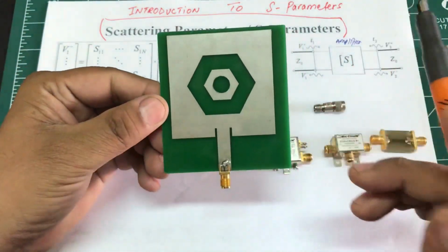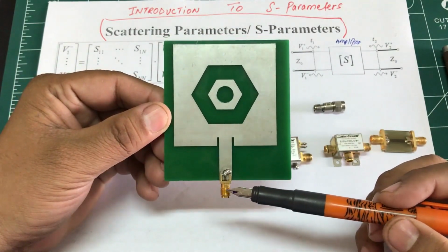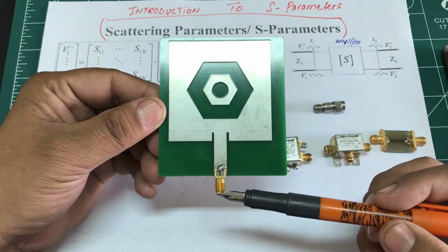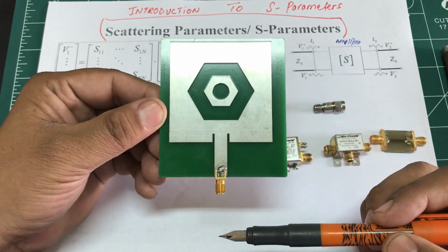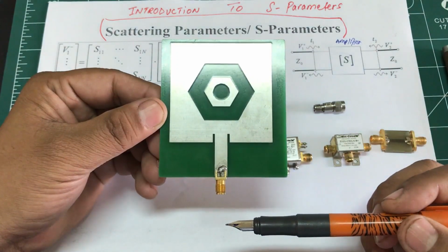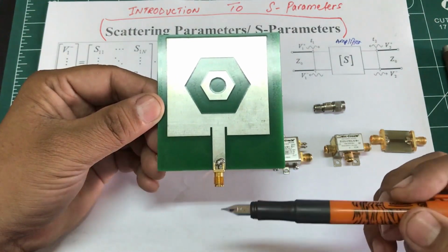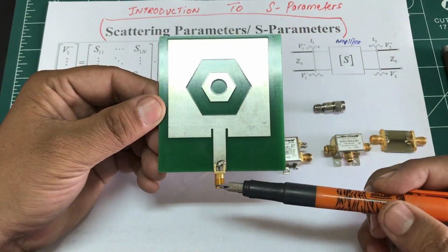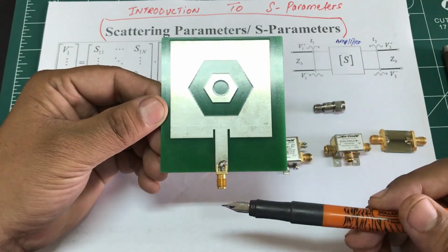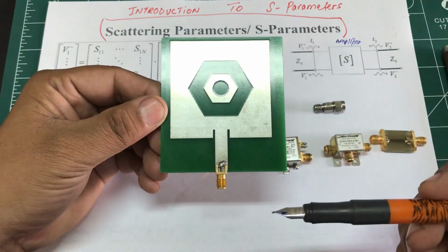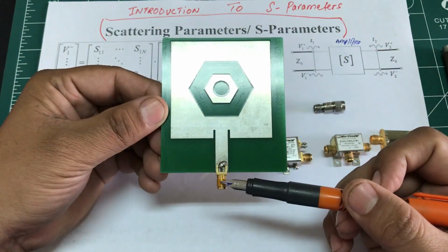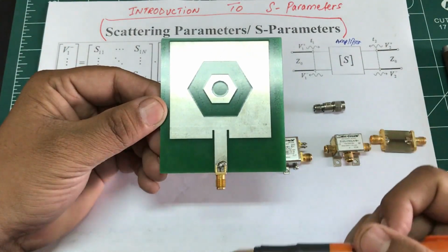This antenna has a single port, so we are only interested in single port analysis of this. When I input some voltage into it, due to the mismatch here, how much voltage is being reflected back? So the S parameter is about the voltage that I am giving into my port, due to mismatch. Now, the mismatch is going to be between what and what device? The mismatch is going to be with the source that I'm using to provide power. The industry standard is 50 ohms, so if this connector is not matched with the 50 ohms of my source, because sources nowadays are usually 50 ohms, and the impedance of this device is not 50 ohms or 75 ohms or whatever it is, then I'll have some reflected voltage being reflected back into my system.